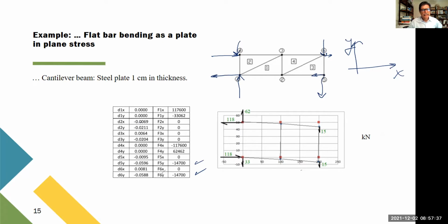Yes, doctor. Okay, so remember, it's not only 1, 2, 4, it's all the forces in the vertical direction, they have to cancel. Summation of all forces in the vertical direction. Also the summation of all forces in the x direction has to cancel. In this case, you have only two reactions in the x direction, at the two joints. So the two have to be equal to each other and in the opposite direction. And this is something that you see here. This is positive, this is negative. But I have to check because it looks like it doesn't coincide.